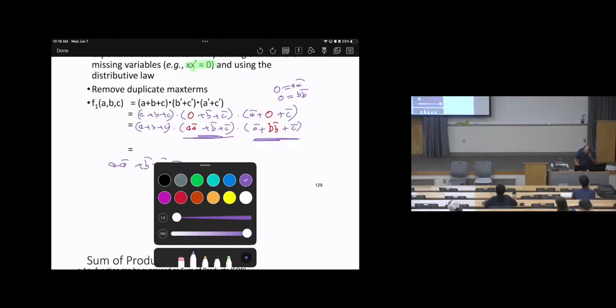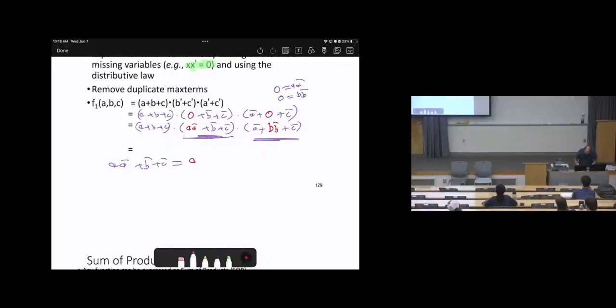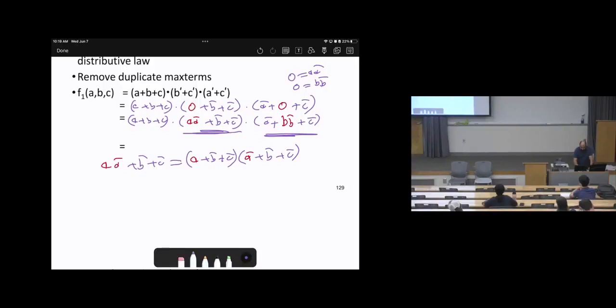So it will be A plus B bar plus C bar times A bar, and I'm going to make this in red color, times B bar plus C bar. So we see the difference is just making the multiplication, put A here, put A bar here. That's how we do the simplification. Take it as a rule.